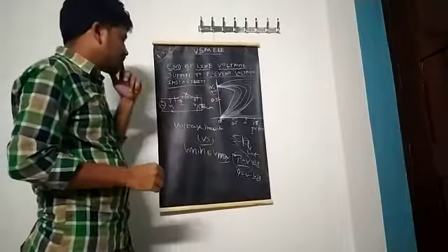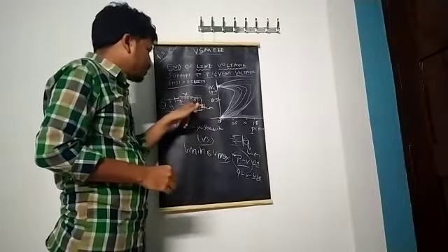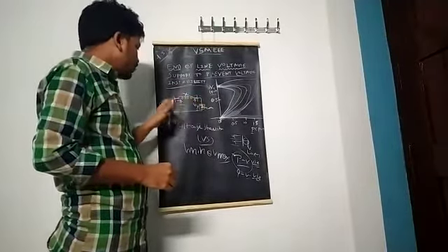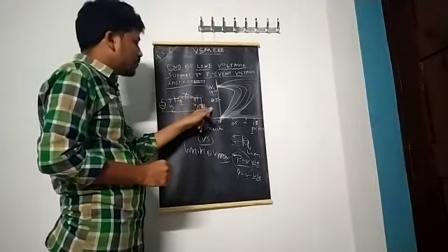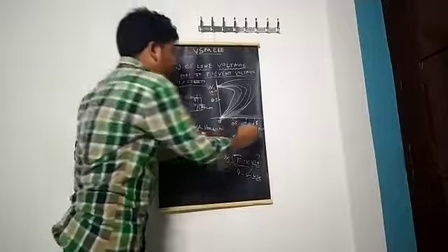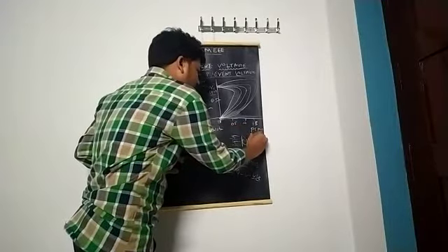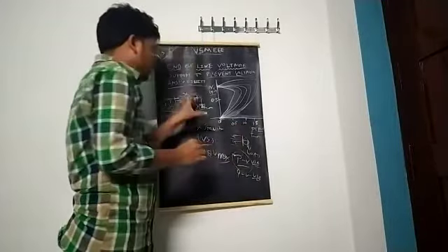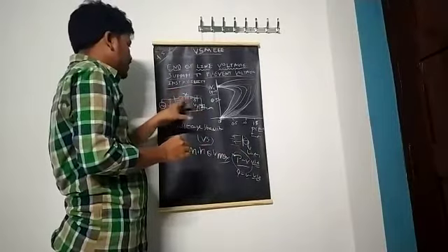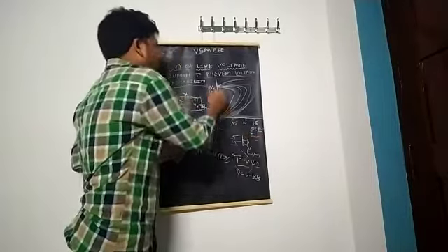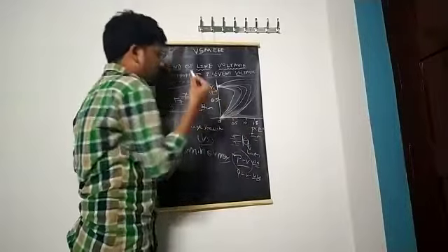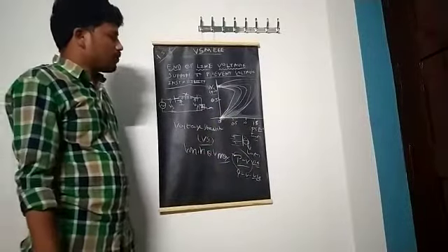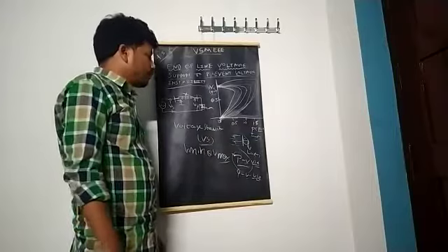That's the reason the P versus V curves are drawn at the receiving end, not for the sending end voltage and sending end generation. We always concentrate on P, the load power. Here P is in per unit, and the power is the load power, the power the load receives from the generation, and VR is the receiving end voltage. This curve is the P versus V curve, the power versus voltage curve.